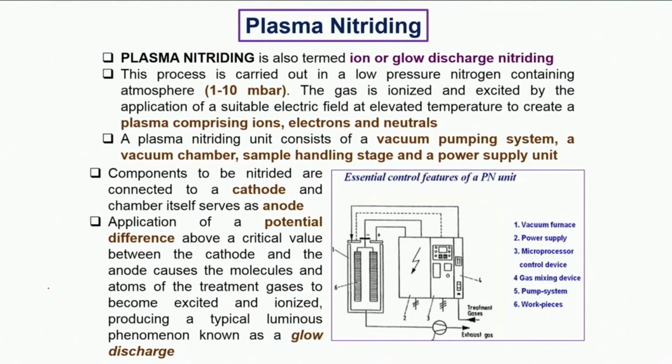The process of plasma nitriding is sometimes also referred to as the glow discharge process, because you do see a blue-violet glow surrounding the sample in the nitriding chamber. Essentially, that glow comes from the presence of particular ions, particularly the nitrogen ions.